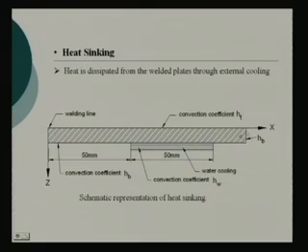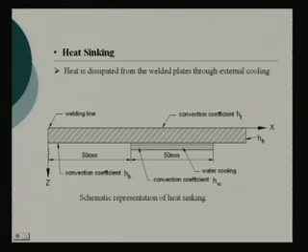So, heat sinking as a method is quite effective. In fact, in practice people have tried keeping dry ice, just putting dry ice on both sides of the weld line. Dry ice means solidified carbon dioxide. What we felt is that it becomes a little expensive, because we will have to have dry ice, and a huge amount of welding will go on.